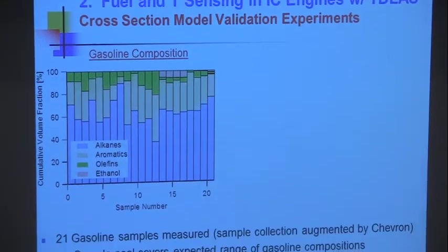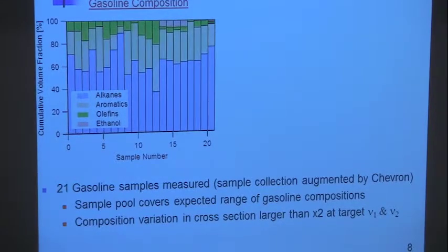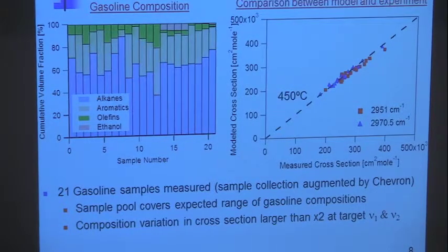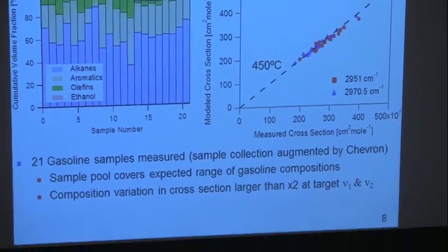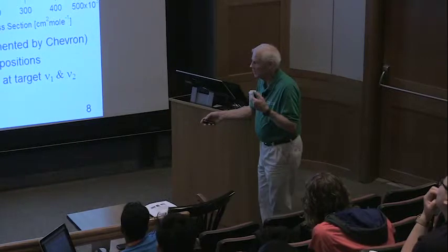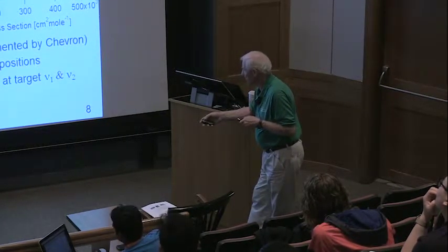And then from these spectra, I should also have said, not only can we calculate the spectrum, we can pick the colors that we want to use for quantitative measurement. So we're going to pick 2 colors, from that model and from the 2 wavelengths that we picked. Taken together, they would give us temperature and allow us to say the amount of the gasoline. So what does the engine company want? They wanted us to tell them the fuel-air ratio near the spark plug throughout the cycle. So we have to measure the concentration of the fuel to get there.